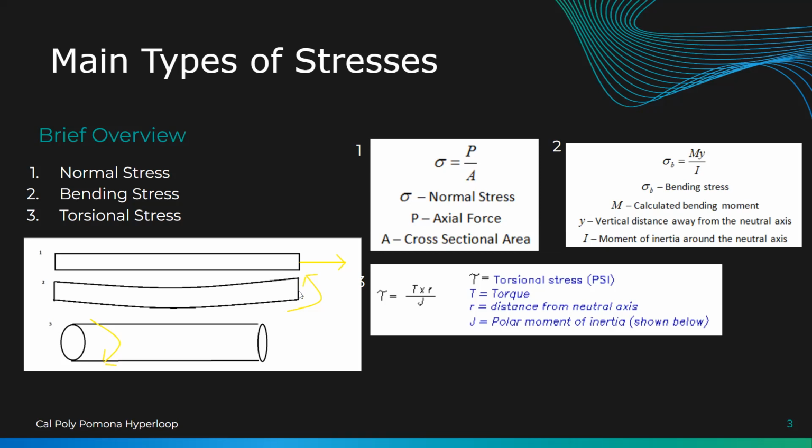So if you want to go to the very top, then Y is just going to be from the center to the very top. And if you want to go maybe not to the top, only 50% there, then it would be 50% of that distance. And as you can see, this bending stress decreases linearly with the vertical distance. So the maximum bending stress occurs at the very top and very bottom, and then it decreases in the middle.